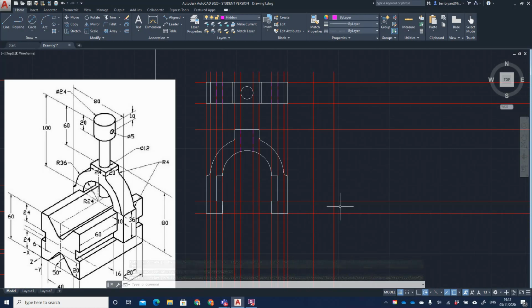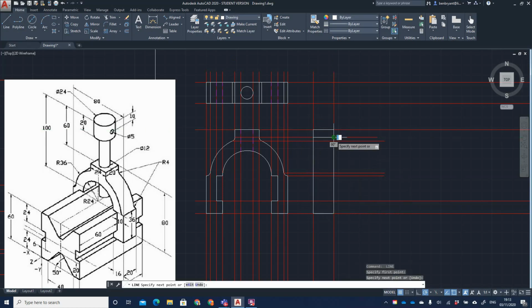Okay, thinking again, all I'm going to be seeing is in the edge. So I'm just going to pop on a couple of final construction lines. And again, sometimes it is just easier to draw rather than working out the offsets, because you can pick up the snap points a lot easier. Okay, so I'm just going to draw my outer shape now. Looking side on, I'll see the top of the fillet, I'll see the base of the fillet, and we'll then again see the top of the bottom fillet.